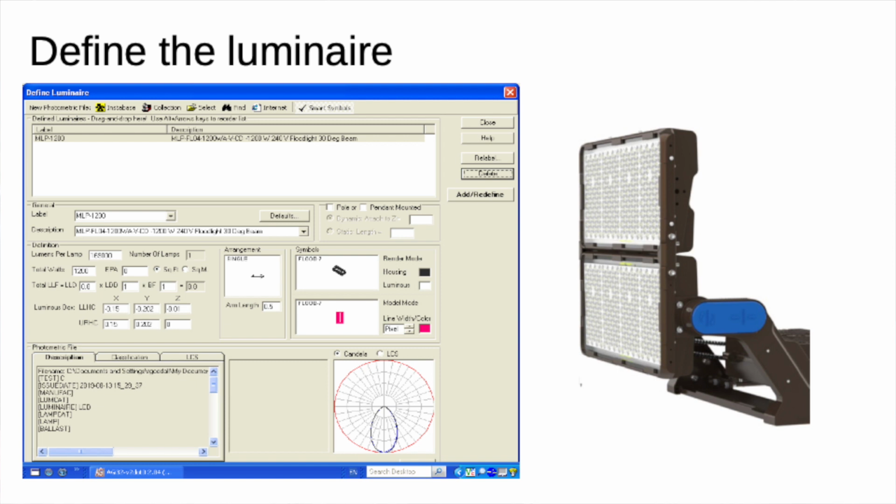And then once we've picked the fitting we're going to use, we define it, we add it into the drawing. Okay, so when you're doing a design, we actually do take the long-term losses of the light into consideration. So in 5 years' time, we know that it's going to be at a minimum of... Correct. If we say that something's designed to 100 lux now, it's probably in reality 120 to 130 lux now, so that at end of life it's down to 100 lux. Which is still compliant. Exactly right.